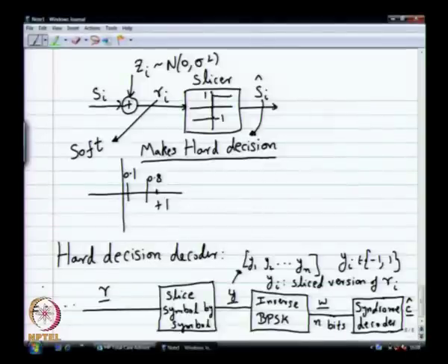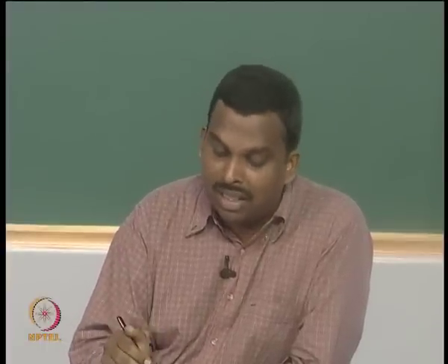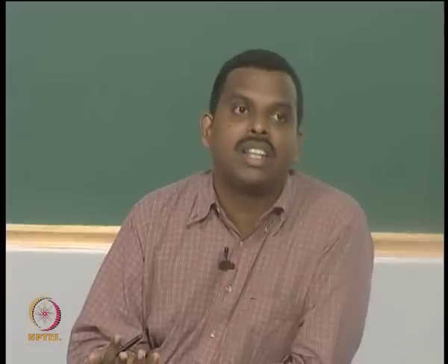So, from the code word to W, I have a binary symmetric channel. So, clearly the syndrome decoder is an optimal ML decoder, you get it. Okay, so this is the hard decision decoder, and this is the same picture like we had before. You are really not doing coded modulation here. It sounds like I am doing coded modulation, but the slicing symbol by symbol is basically an independent demodulation. I am not taking the coding into account when I do slicing symbol by symbol.